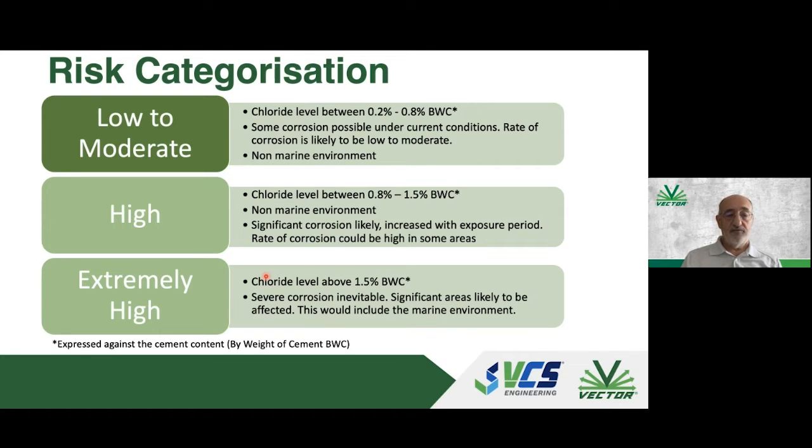High categorization will be if you assume that the rate of corrosion may be significant, and if you know the chloride concentration is up to 1.5%. And then there's the extremely high, obviously, which is above 1.5%, and it could be a marine environment, for example.